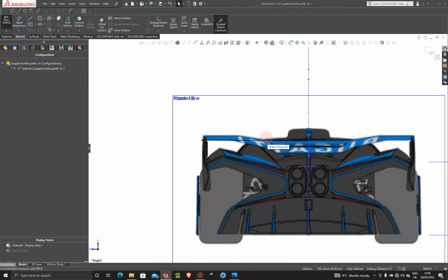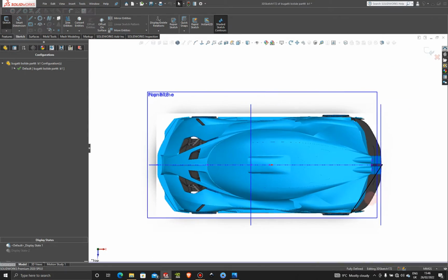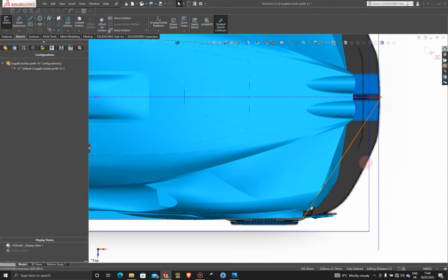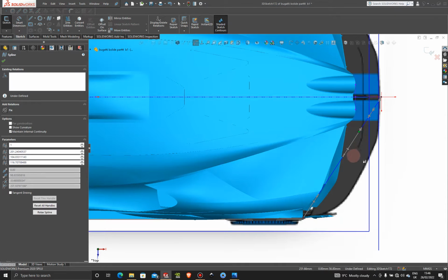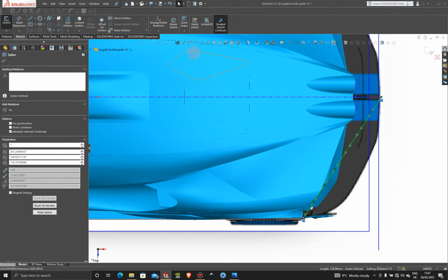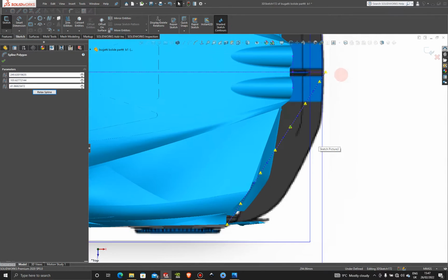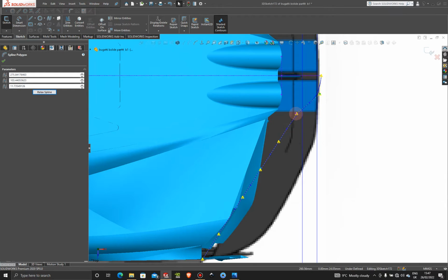And then firstly we're going to adjust our spline to fit this edge here. Okay, so let's add a few spline points. Let's add one here, here, and then maybe one more over here. Hope it's not too much. And then just click on this line, and then bring up our control polygons, and then click on this point, and then we're just gonna come in here and set our spline to fit that.